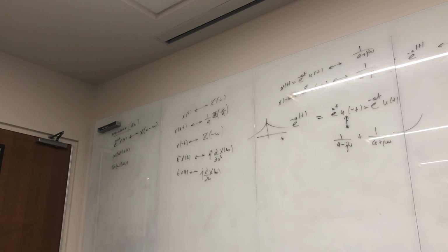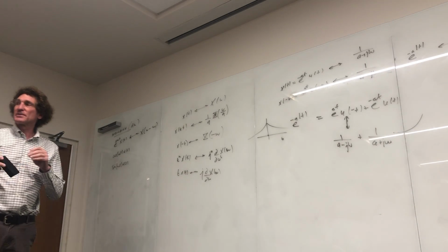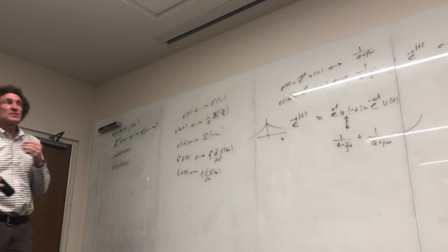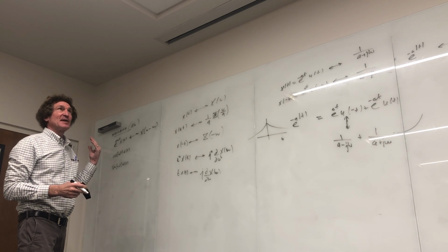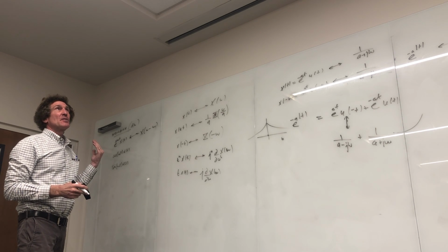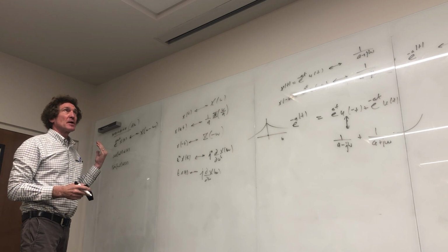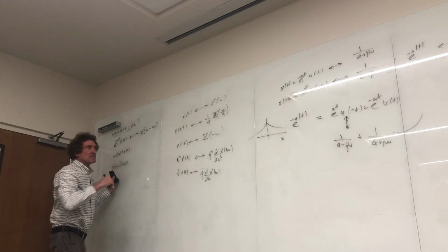Remember how much of a similarity this stuff is to the properties with Laplace, right? Only now instead of s, we have j omega. And most of the time, if you just replace s with j omega, you get the exact same thing. As a matter of fact, you do for all functional forms that have non-infinite values at 0, and their values are only true for t greater than or equal to 0.